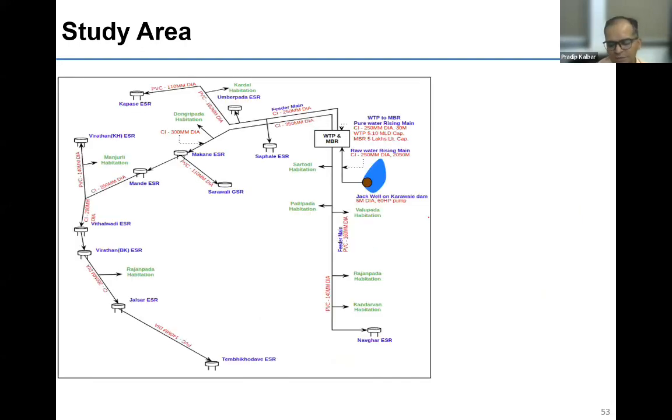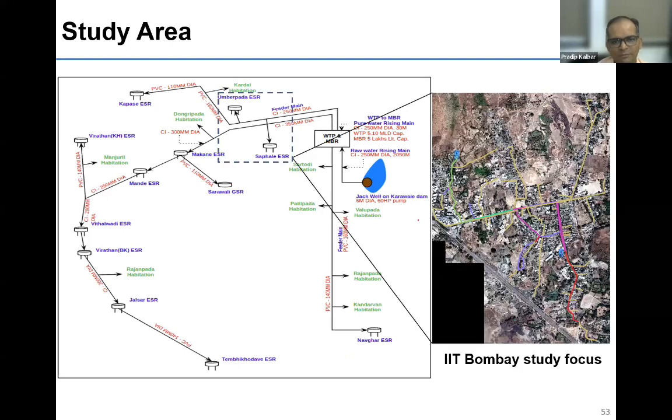When we visited in 2017 as part of a DST funded project, this tank, Safali ESR of 1 lakh liter capacity, was not operational, and the operators were bypassing it because it was leaking. There were huge leaks after a few years of operation. They were asking to construct another tank. I suggested, let us try a shaft and see the results. The Safali Gram Panchayat agreed.